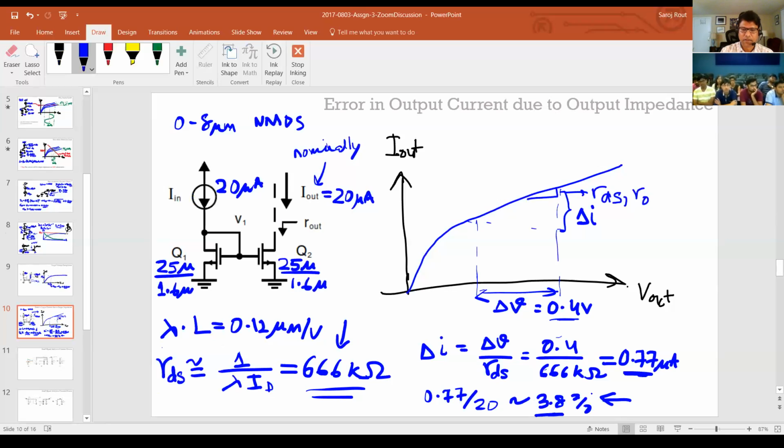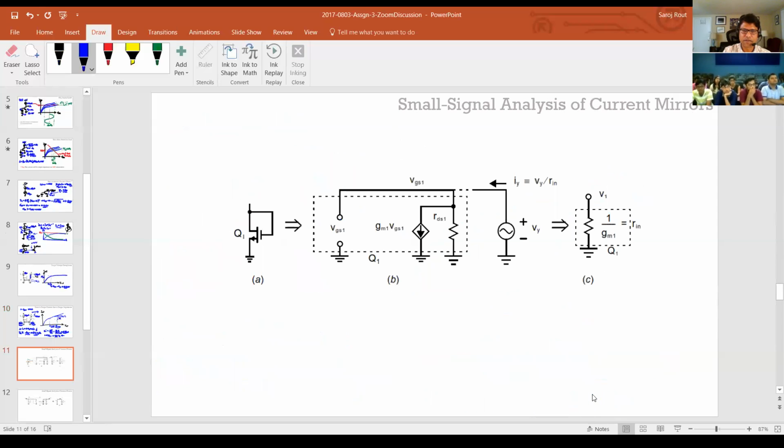Okay. All right. So we're looking at it in a large signal model, but when we do a lot of our small signal analysis, this serves either as an active load or even as a current mirror. When we do small signal analysis, we need to find the small signal equivalent of this, right? So we follow the same approach. I won't go into the details, but I'll just quickly touch on how you find the small signal model.